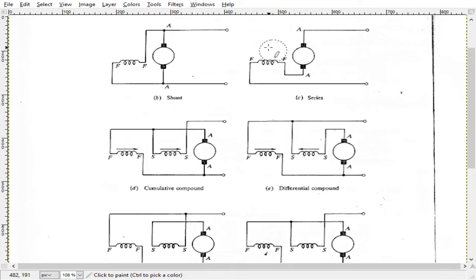Okay, so here in this first drawing, this shunt winding would not exist if it was a permanent magnet motor, and so what you would have is just the armature winding, the armature here, and a permanent magnet which generated a magnetic field, and the armature is rotating inside the magnetic field that's generated there. So anyway, that's permanent magnet. Now, those are called permanent magnet motors and generators.